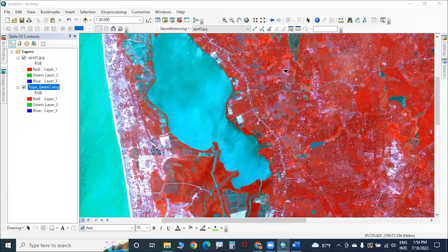Right? If you use the global datum, it is very difficult to click. Because it is not accepted. Why is it not accepted? These coordinates are in the national grid system. Right? Those two coordinates are different.